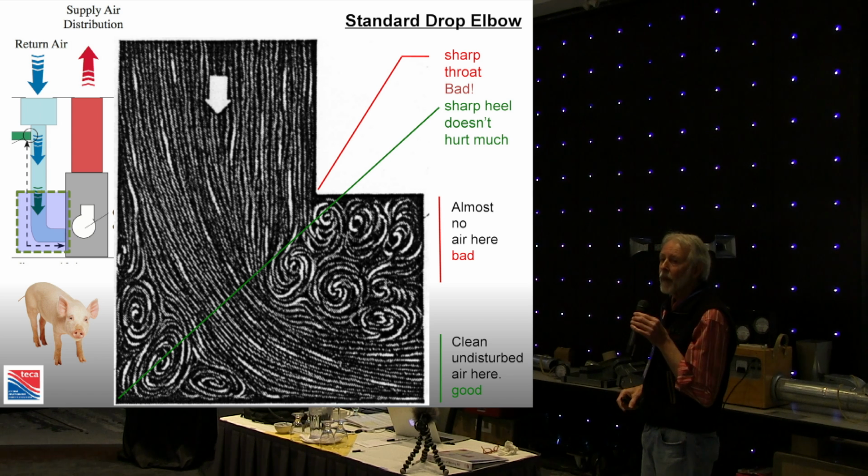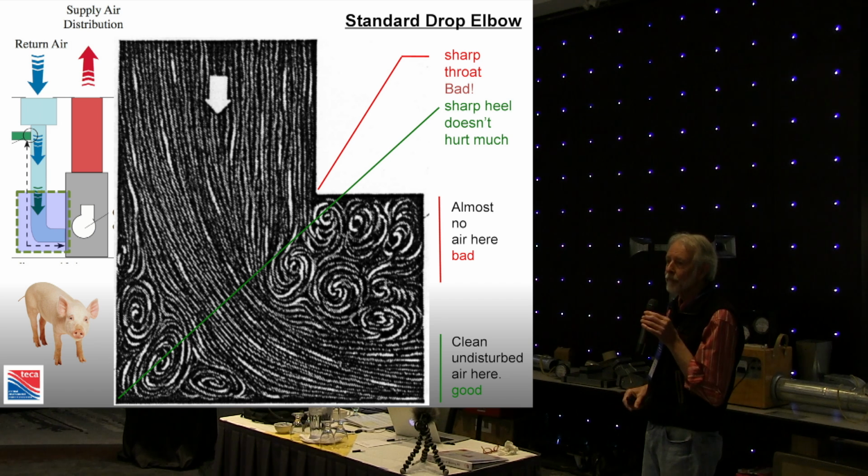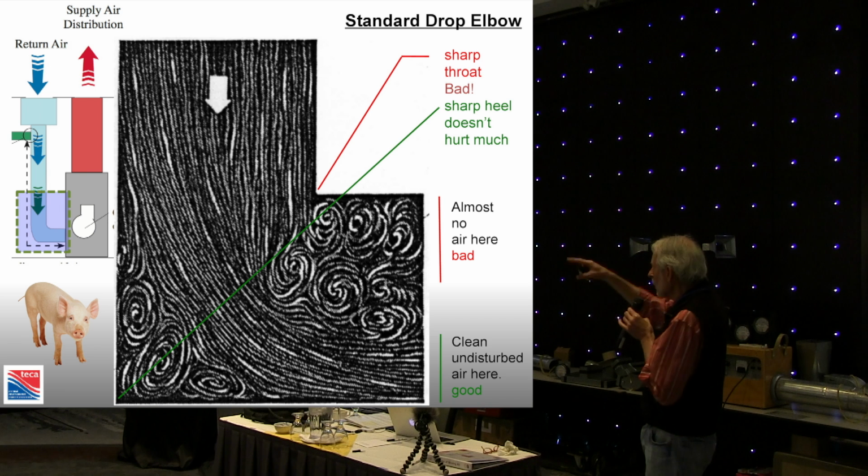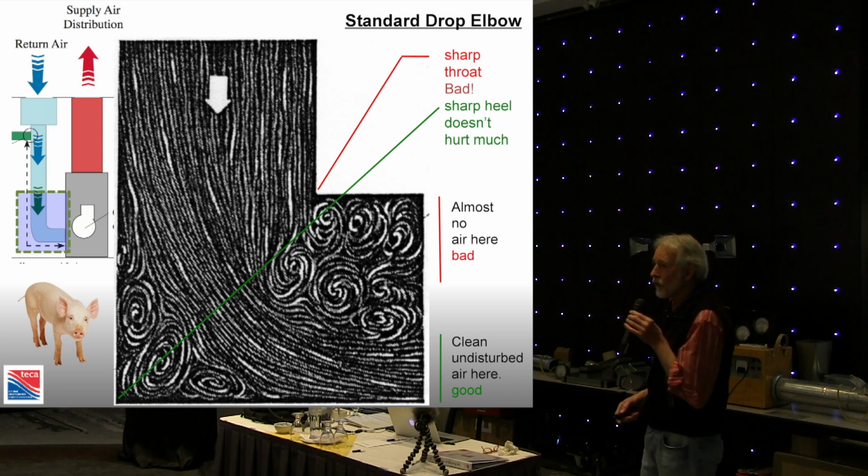99% of you will. Have you ever pulled the filter out and looked at how the air is distributed, how the dust is distributed across the face of the filter? Next time you do, look for it and you'll find that the bottom 1/3 will be filthy, and the only time the top 2/3 becomes dirty is when the bottom is so bad no air can go through it, and the air will start to curl up and go through the upper half, the upper third.